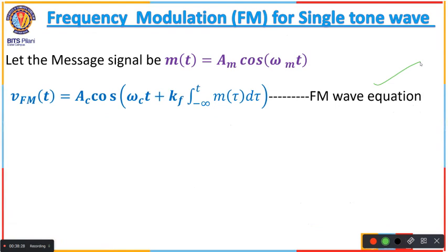In the same way, you are going to use something called a tank circuit along with the transistor, right? The tank circuit will oscillate, right? And after some time it will get damped, right? To keep that going, you give that output as an input once again, so that it will continuously oscillate. That is called an oscillator.